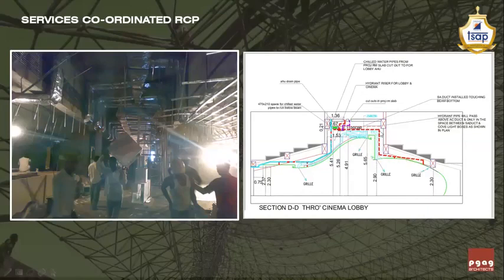Because of that only, you are supposed to know the diameter of the pipe and the width and size of the HVAC duct. When you correlate all your false ceiling dimensions with all these services, only then is it possible to execute it as per the required height, as per the heights which you have shown in the tender stage.